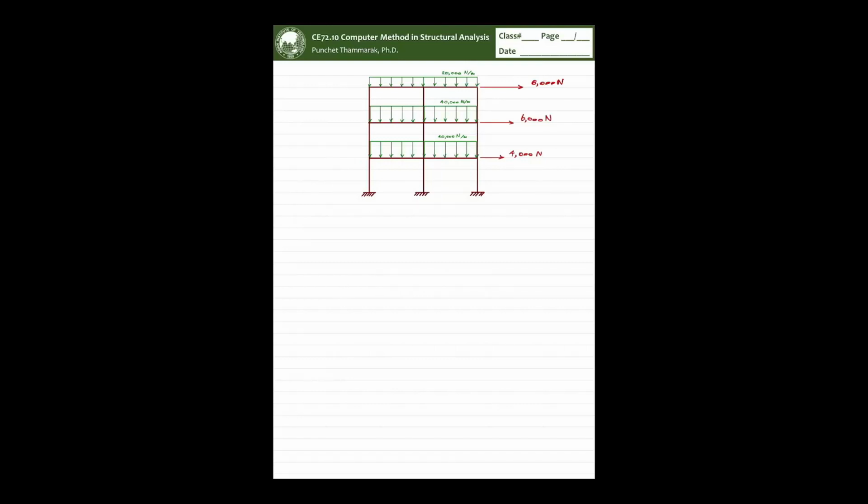See if that should be believed or not. If the slab goes but the beam doesn't go, that means the beam doesn't carry the load. And what's wrong with that? Maybe the node, the restraining, like the connectivities between the degrees of freedom, the vertical degree of freedom between slab and beam, are not connected well. It could be the default of the program. If you don't make the link, it doesn't connect. It could be that way. It's not like you make the model of the building, make slab, make beam, and the program will understand that this slab is going to move along with the beam.